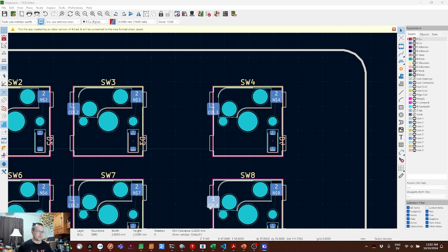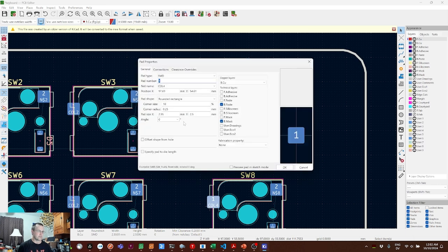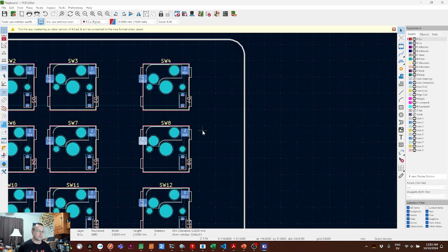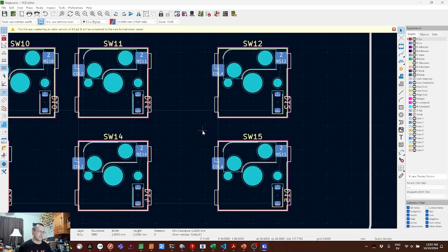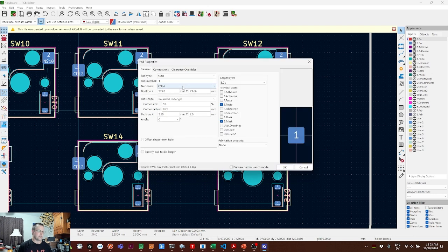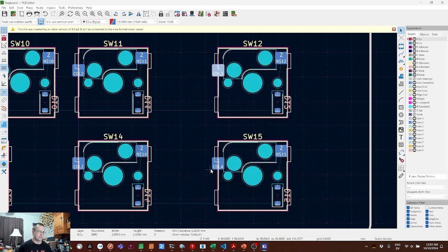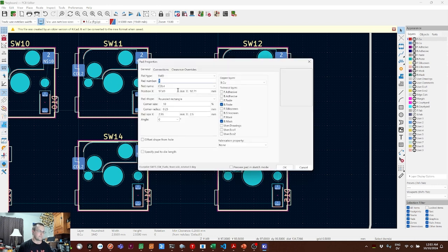Now, if you have any background with KiCad, you may be surprised that we're not doing this in the schematic editor. This particular layout generator doesn't create a schematic for our circuit. We're just working with the netlist that it provided. If you were doing a more complex circuit, you probably would want to build the schematic view and drive everything from there, but this way works just fine for a simple circuit.